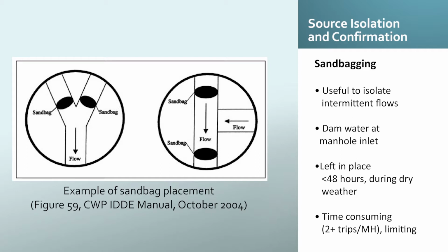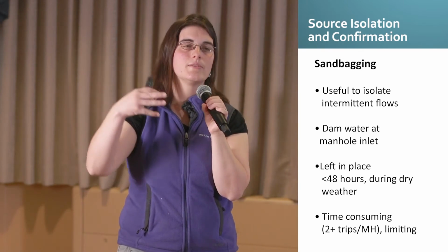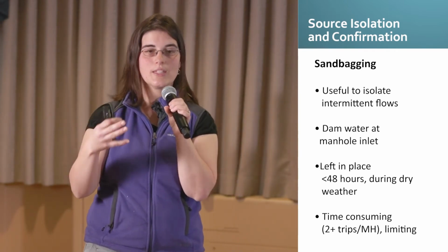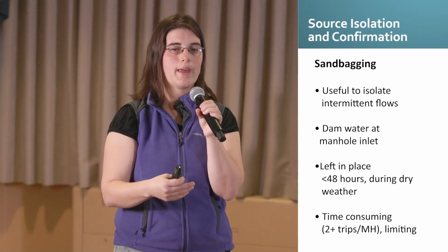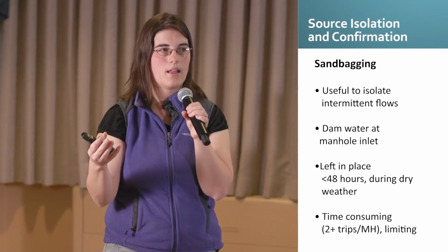Your sandbags are left in place for about 2 days, 48 hours or less, and then during dry weather, as I mentioned. This method is a little bit time consuming because it requires multiple trips to the same structure and it has limited results. But essentially what you're trying to do is just trap, if you have an intermittent or a continuous flow that you can't see while you're there, you put the sandbags in, it traps it, and then you can collect a sample of the fluid coming in and analyze it.